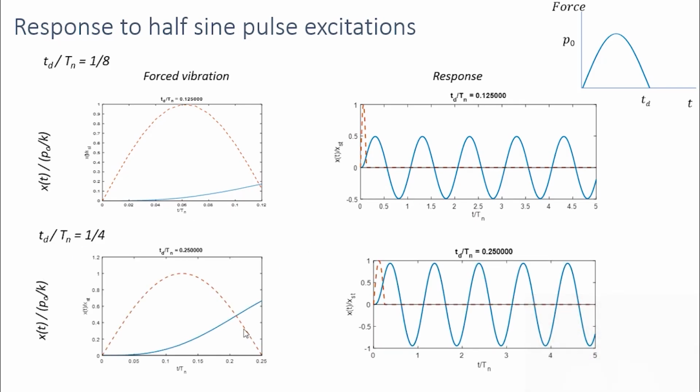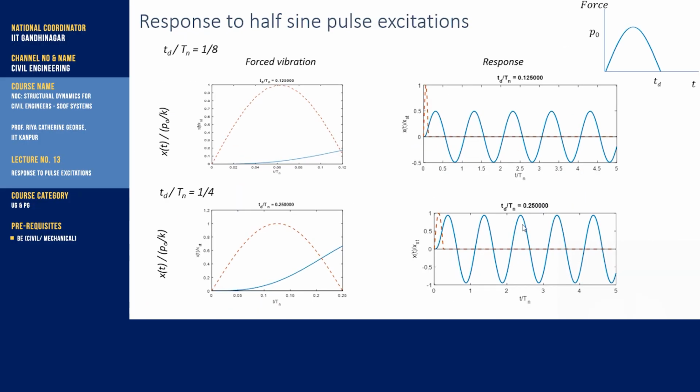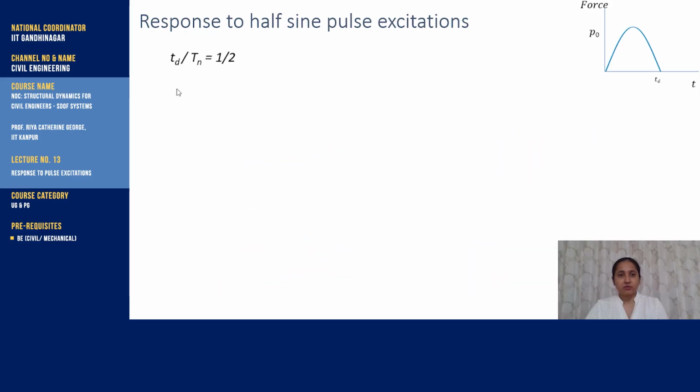The similar pattern continues. As the duration of the force increases, the dynamic response also increases, and for some durations the dynamic response is more than the static response. Here also the maximum response is during the free vibration, after the pulse stops. Now let's see the response for Td by Tn equal to half.